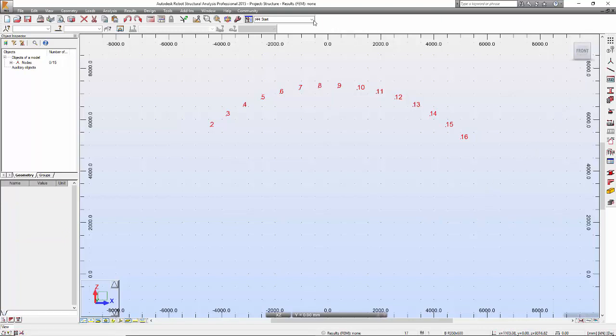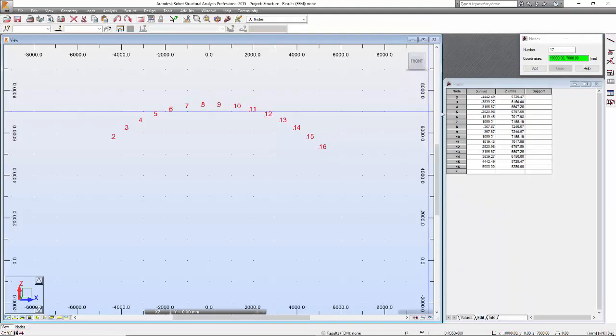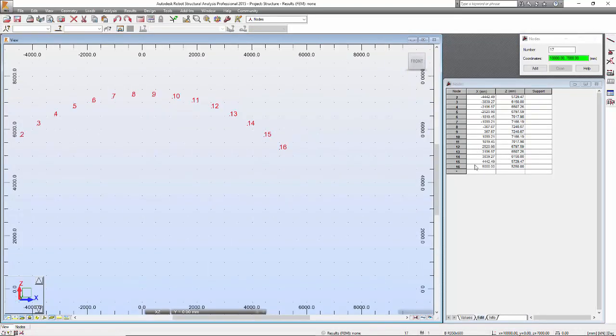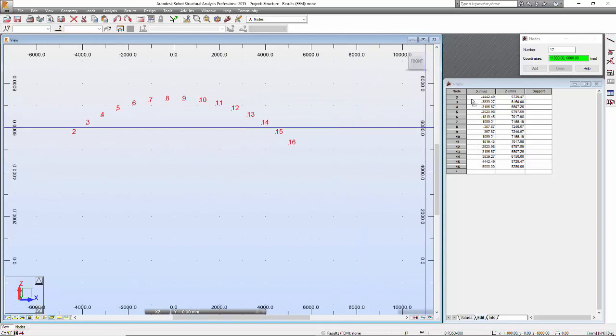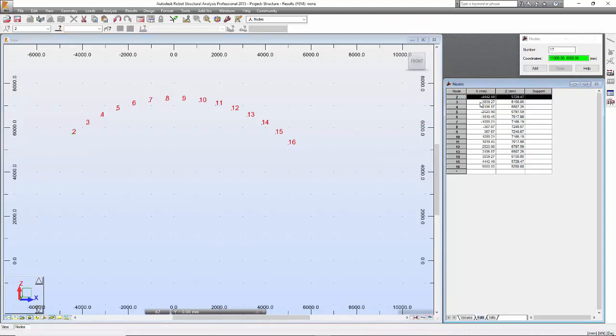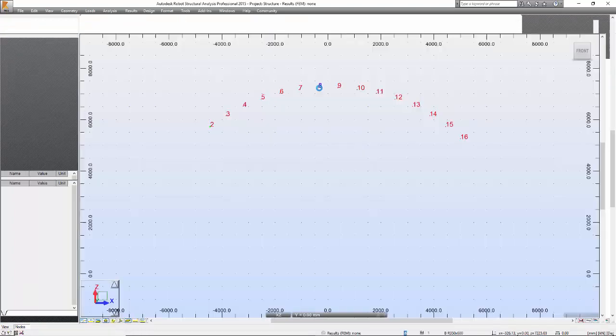And then after that, you can have a look at the nodes you generated, and possibly there was a mistake already, because the first node is not from node number 1 anymore. So this possibly will create a problem for you, because all the coordinates we generate are 1 to 2, 2 to 3, 3 to 4, and so on. So once you have this problem, what we need to do is come back to the nodes and delete all these structures.